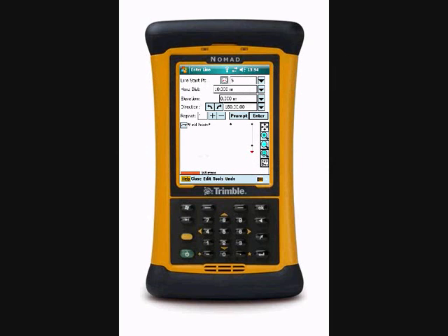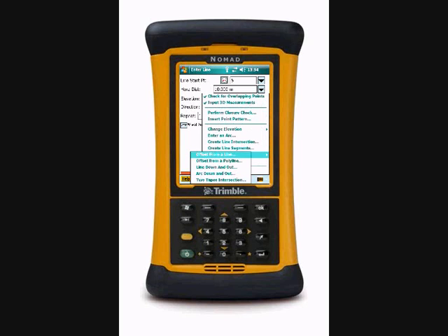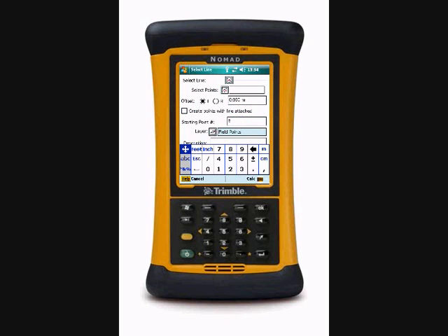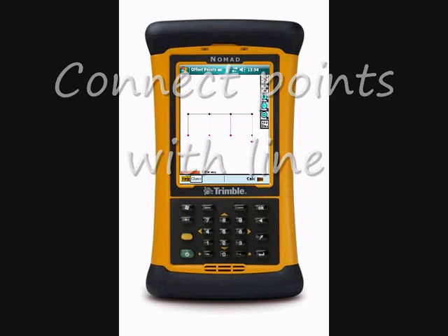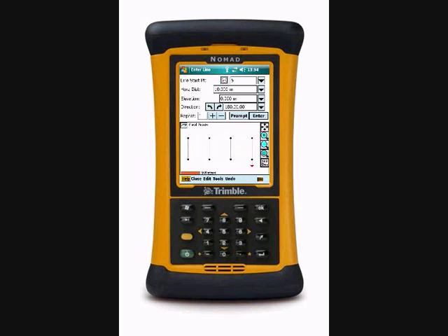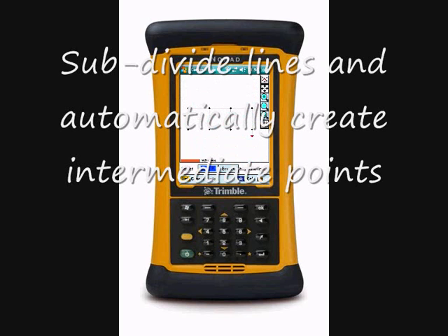We can now work with offsets from the points we've just created, and to do this all we have to do is choose the points we wish to offset. Just select off the screen. Again, choose the horizontal distance and then which direction we want to go. In this instance we're going to add the line work at the same time, so that's the offsets. And now we just connect the bottom points by choosing the start and end point.